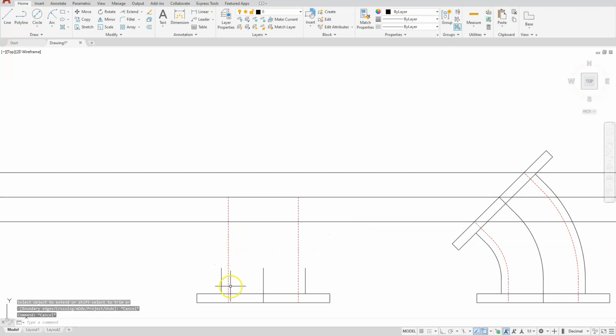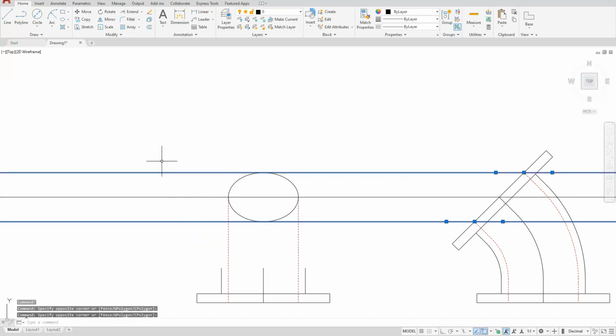Okay, so with this we do have a location of where our ellipse is going to be. We do have this one specified by the axis endpoints. So I'll go to the ellipse and I'll choose axis end. Select this endpoint, to this endpoint. And then I'll go up to where it perpendiculars here. Let's go ahead and erase the top and the bottom line.